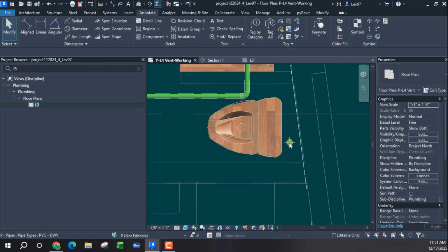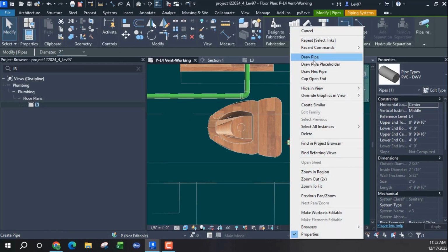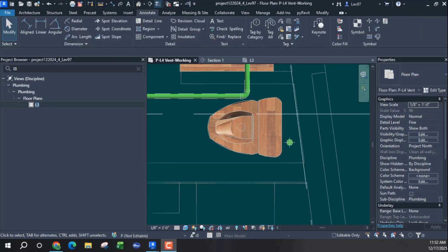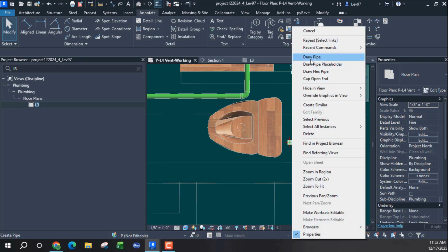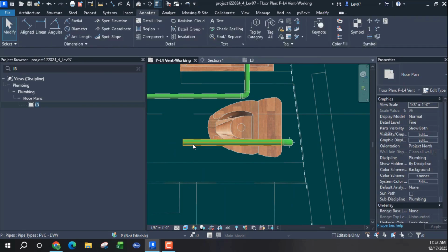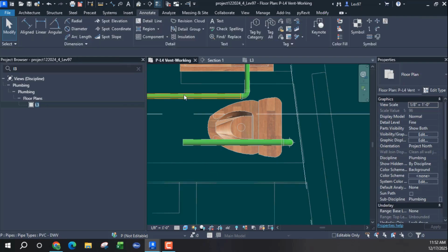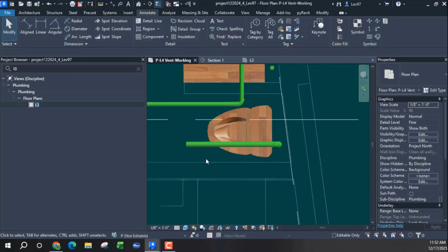So this is at 9, so I'm gonna, that's a 2-inch, okay. So we got this. So what we're gonna do is connect, let's draw this pipe. Gonna come over, but I need to change the elevation to a 9. It can go either way. I'll just go this way. 9, is that 9? 9, okay, so we're good.